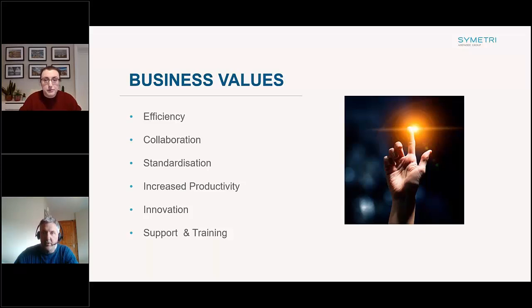I'm just going through the questions there. One of them was, when you were showcasing the exporting of PDFs and the likes, if someone was to export PDFs and NWCs, does it affect the time to print the PDFs? So it's going to run them in sequence. Depending on the configuration you have set up, and the order that you've created them, it could do your PDFs first, or it'll do your NWC first. So it's up to you which one you want to export first. You can order that list, and whichever is top of the list is going to run first, and then it will move to the next one and the next one.